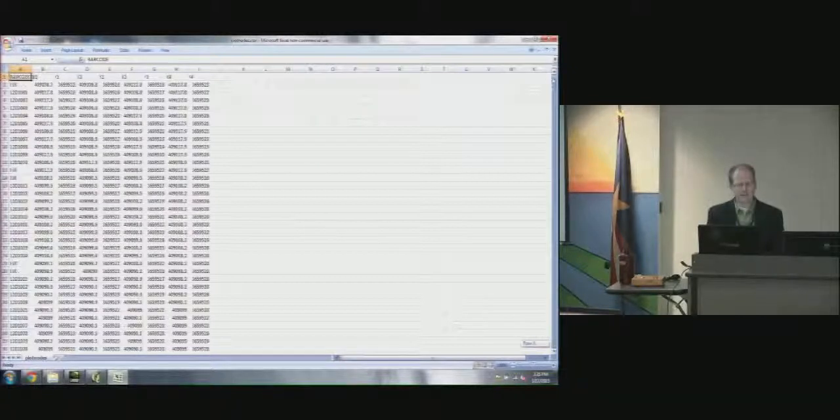And as I mentioned in the talk this morning, there are pairs of XY coordinates to mark the corner locations of those plots. So these are UTM coordinates. The X would be the easting value for UTM zone 12 north, where we're located now. And the Y coordinate would be the northing. These are meters. So the UTM measures in meters from some reference point.